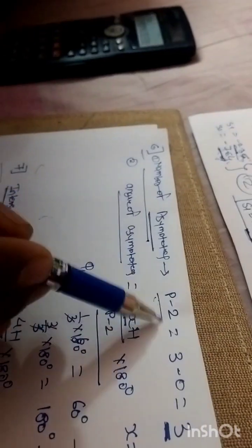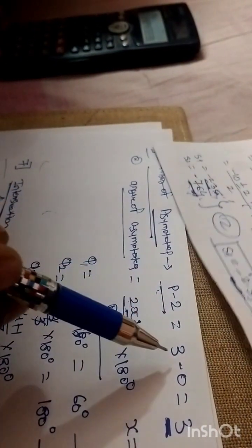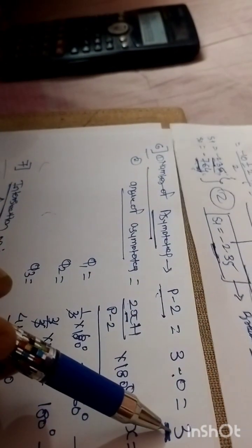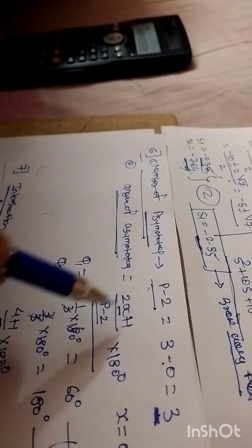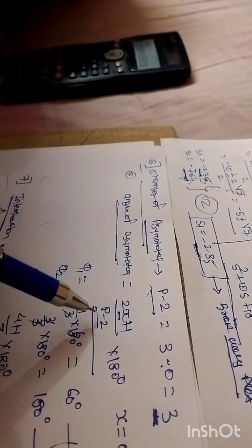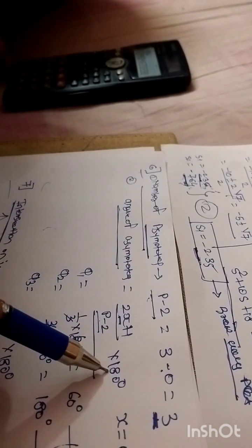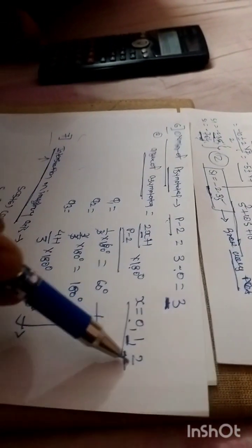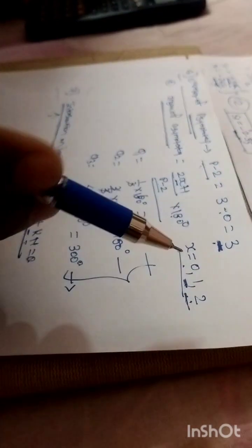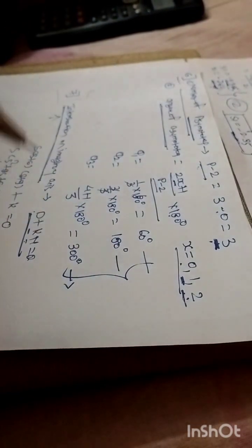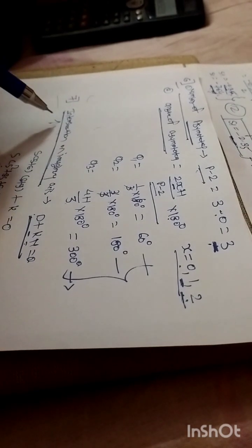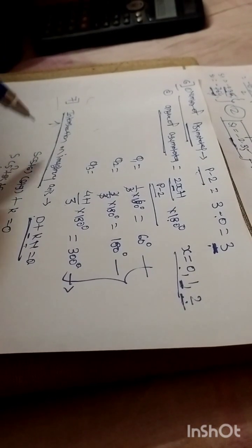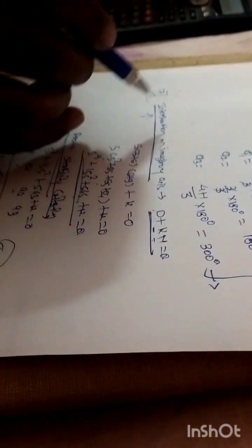Then after that, step number 6, number of asymptotes we need to define, right? Number of asymptotes equals number of poles minus number of zeros. So 3 minus 0 equals 3. Immediately after that, we need to determine the angle of asymptotes. This is the standard notation, (2q plus 1) upon p minus z into 180 degrees, where we follow three iterations in which q equals 0, 1 and 2. Why? Because the number of asymptotes equals 3. So these three are the asymptote angles, right? Step number 7 is the angle of departure, but as we are not having any imaginary roots, that step is skipped.